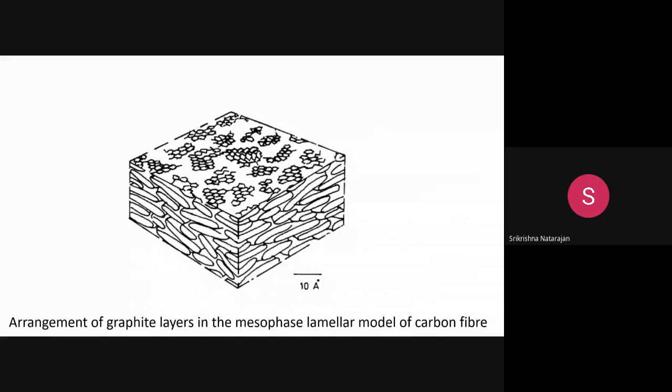So that is the advantage here. By using the pitch, you can eliminate the tension or stretching, so that by doing the spinning process and because of the maintenance of the liquid crystal nature of the solution, you can manufacture the fiber with good mechanical properties like orientation, tensile modulus and tensile strength.